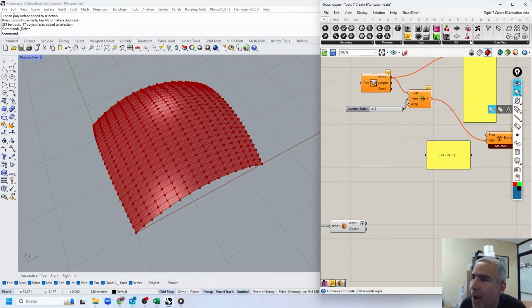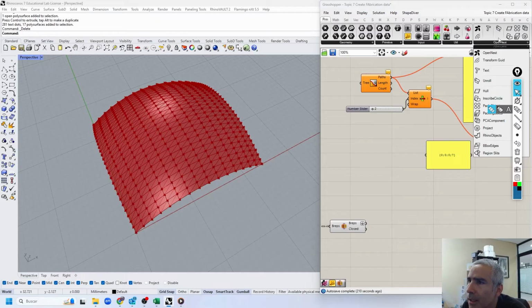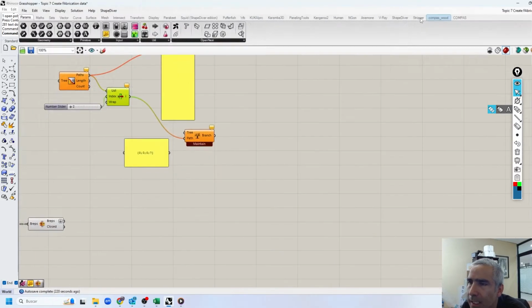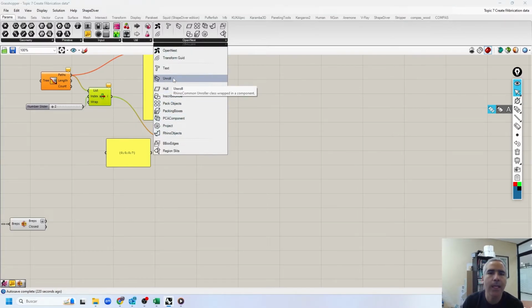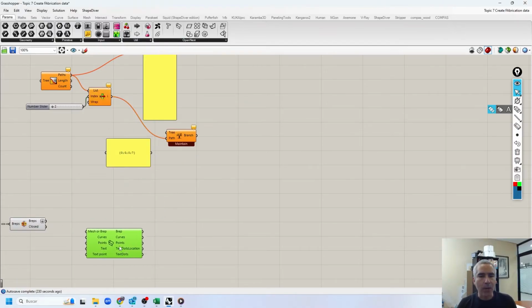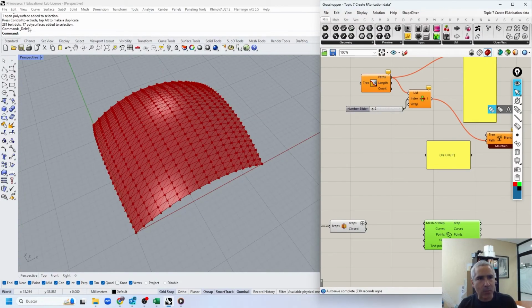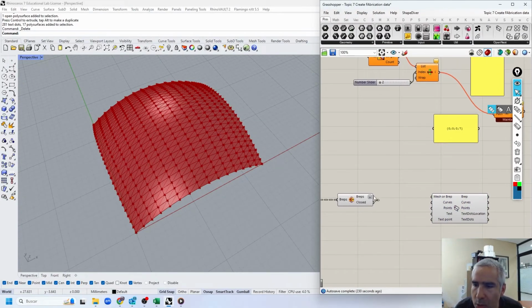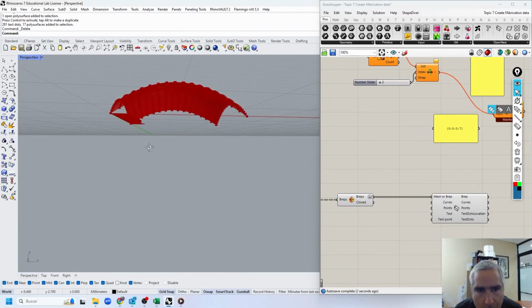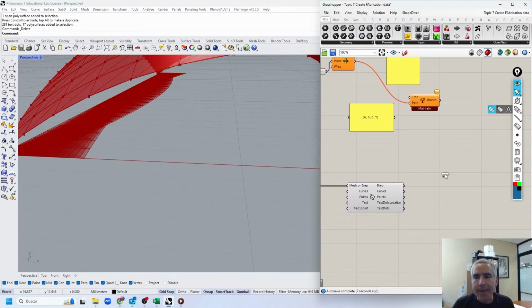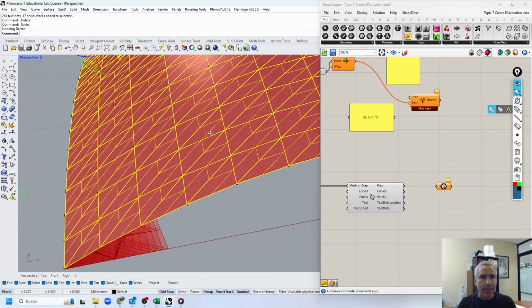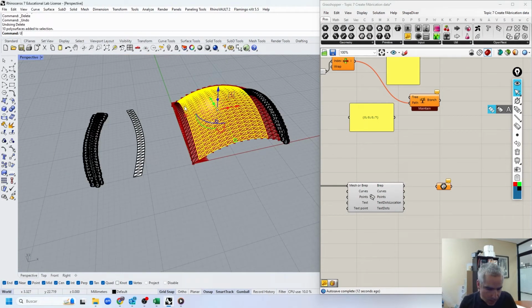And if you installed it correctly, you now have Open Nest over here. It'll live over here in the Parents tab. And it has this unroll function. This unroll function is the same function as the one I just did in Rhino. You basically plug in the brep and it'll do the unroll function there. The problem with that is that it's the same thing, for example, as doing all of this and then unrolling them.